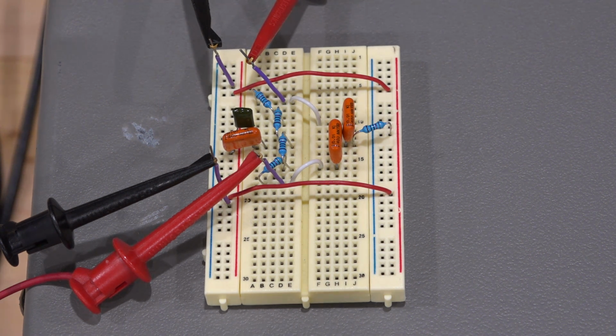What you really want is a dynamic signal analyzer or an FFT-based spectrum analyzer with a high impedance input so you can connect the output of this filter to it. Now I actually don't have one of those, and after fiddling around in the lab I noticed that I do need one, so I ordered one. That's going to take a while to get here. We'll use it for some other future experiments. A spectrum analyzer with a 50 ohm input is not going to work. An oscilloscope is potentially possible to use, but that still can have second harmonics show up. So let's use a totally different method and use something else from Stanford Research to make this measurement.